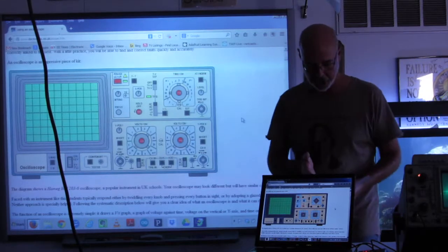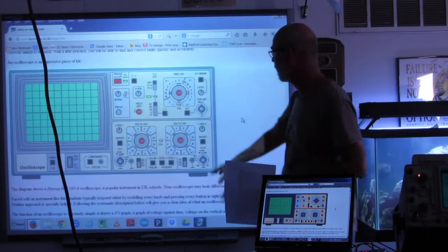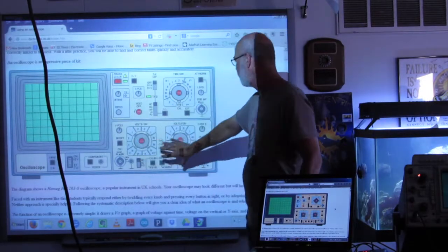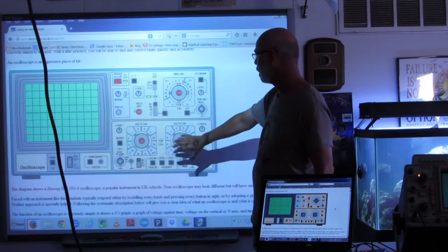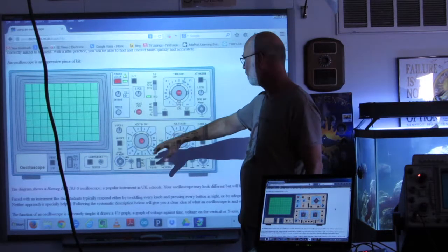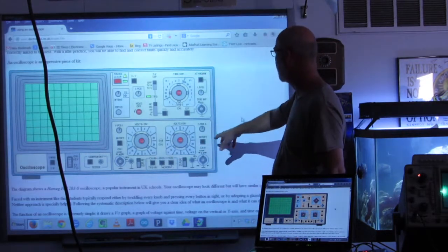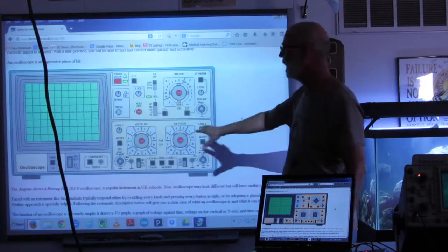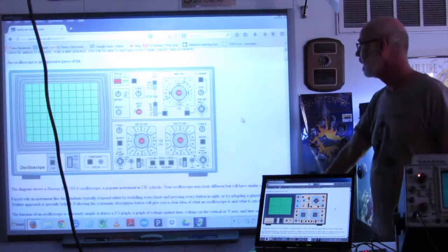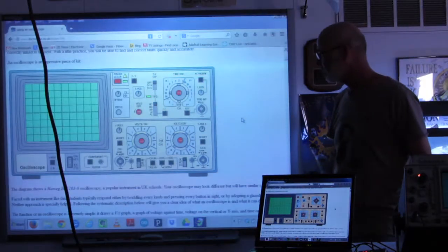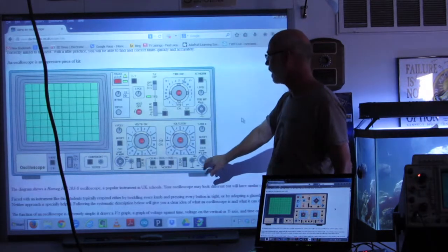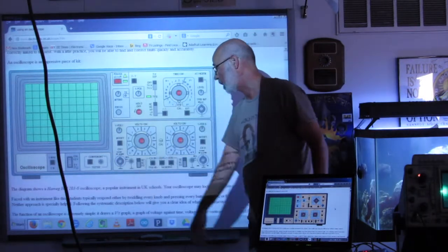Now we come to the vertical channel. Okay, the vertical channel on all scopes. Most scopes have 2 channels. Some toy scopes have 1 channel. You don't even want to deal with toy scopes. Most scopes have 2 channels. Many now have 4 channels. Okay, 2 channels is enough. 2 channels is fine. Each channel has a BNC type input connector, industry standard type input connector.